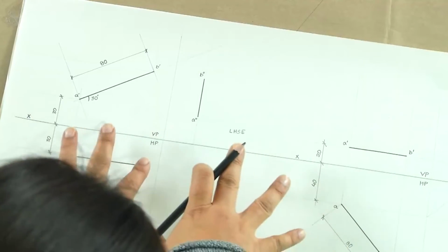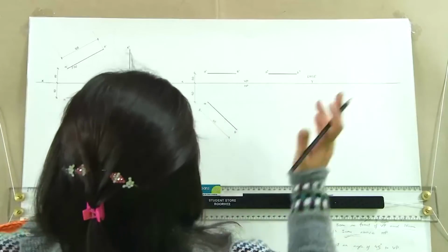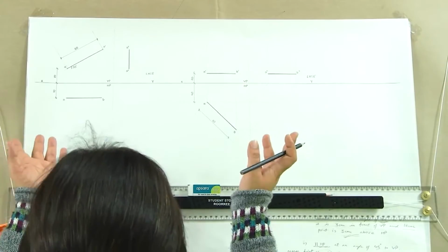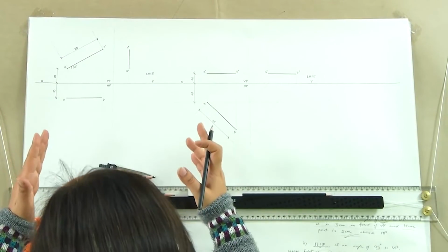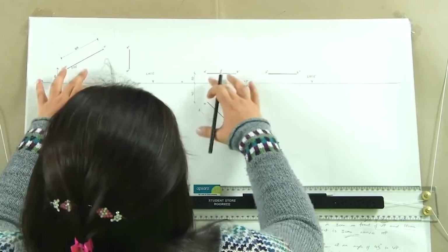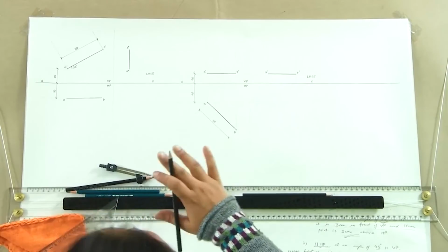Here I have made it continuous. However, if you have say 4 problems to be drawn on one sheet, you should first see how much space each problem would approximately require, and then divide the sheet in 4 equal parts, or unequal also in case one problem requires a bigger solution, and then you should center your drawing in that space available. So, preferably the XY line for the problems, the solutions should be almost in the same line, and then the rest could vary. It would make your sheets look good and also more readable.